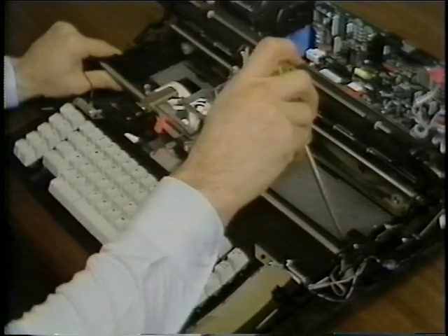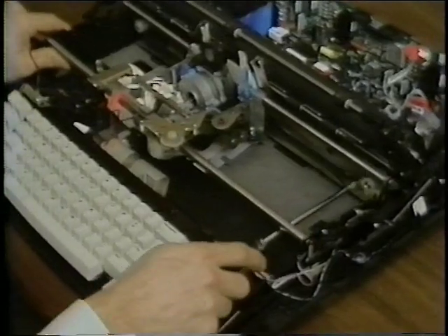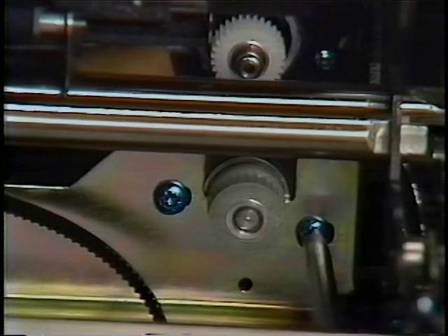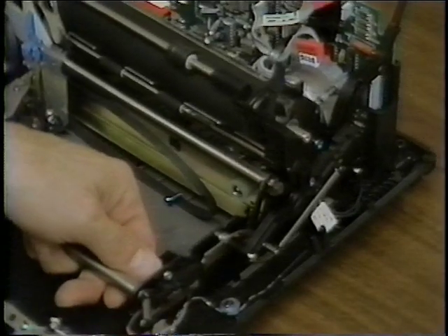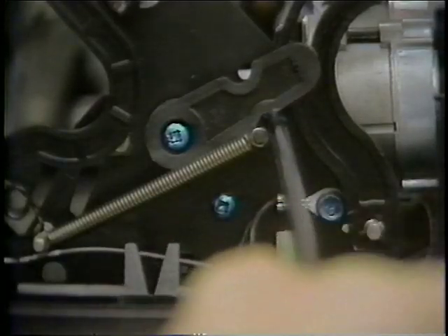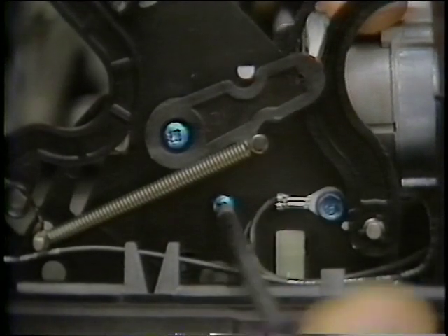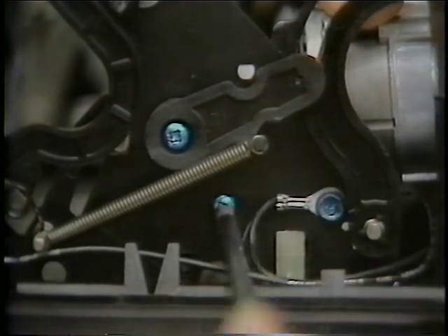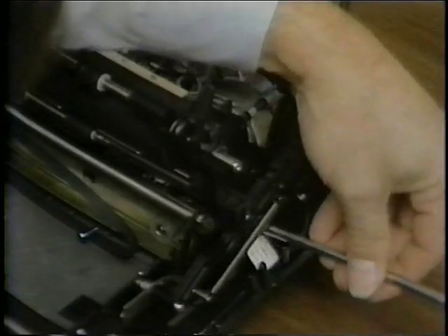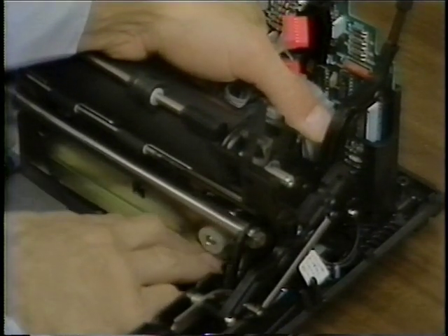Use a screwdriver to release the two front frame latches as shown. Hold the front of the frame assembly up so you can remove the two front transport motor bracket mounting screws as shown. Then remove the two right side transport motor bracket mounting screws. Move the transport motor bracket assembly to the rear and lift it out of the machine.